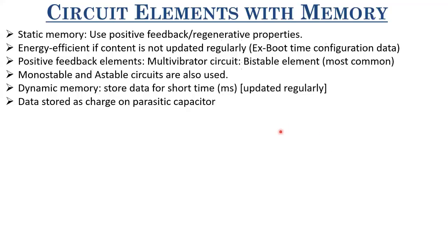Now, we know that there are several problems like charge leakage, because of subthreshold current or diode leakages, as well as the charge sharing problem. Whenever we are working with these high impedance nodes or internal node capacitances, there would be these problems, as well as crosstalk and others. But how can we handle these problems?